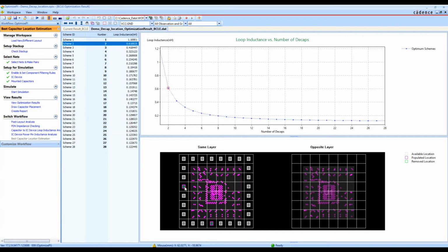If you have 2 parts, it might change it. So it might change the 1-part version. If you have 2 parts, it says put them there and there. 3 parts, it adds to that. Notice with 4 parts, it's moving this one around. But every one is independent. It doesn't necessarily rely on the last one you placed. And you're going to kind of strike a balanced trade-off here of how many parts I should use versus what type of performance I can expect to see from this.